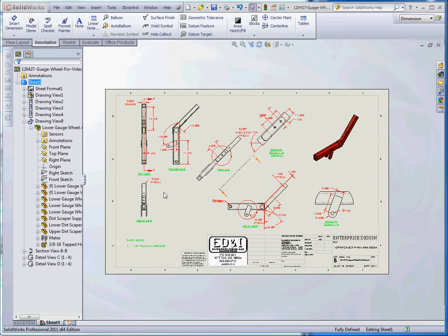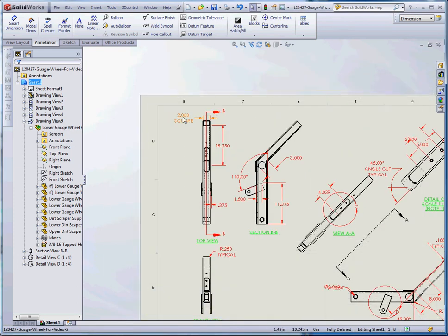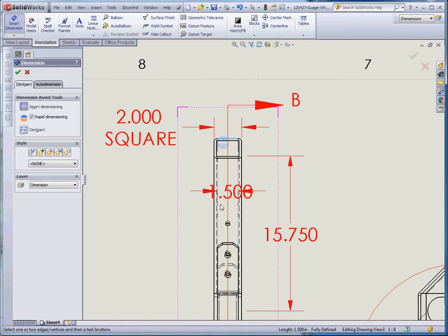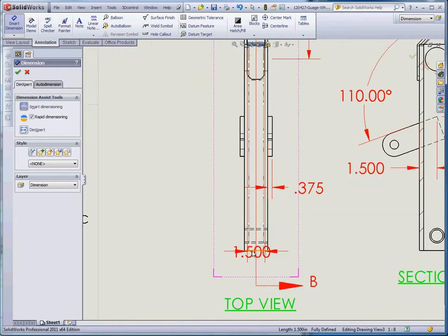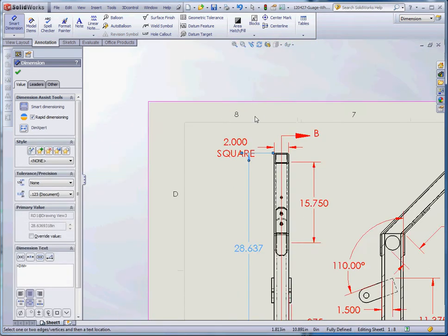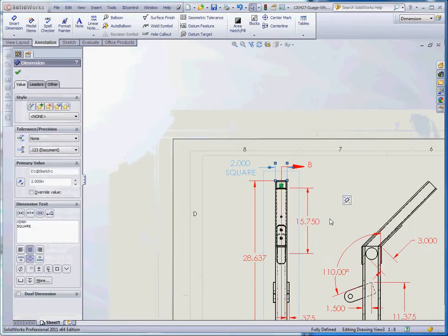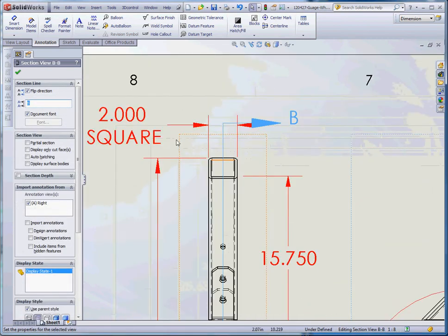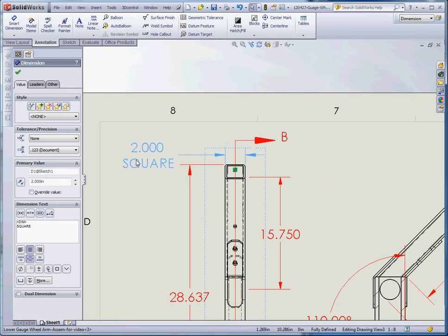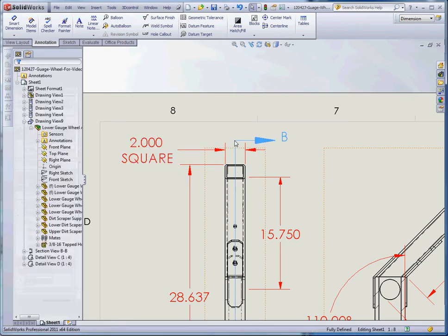So let's go ahead and do this. Let's put in our total length, height, and depth dimensions in here. Maybe it's important to find out what the total length on our ultimate assembly is, if it isn't defined in other dimensions. You simply do that by picking the appropriate references, just like you would for a sketch element. And of course clean things up and make sure you have things pulled out, because this was at a different angle regarding these parts being put in.